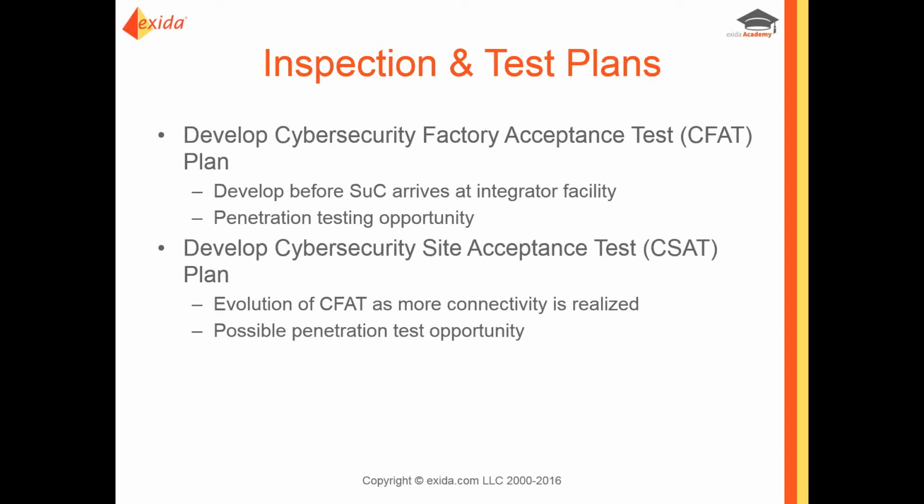You're also going to be developing the cybersecurity site acceptance test plan, after it's been actually installed but prior to startup. That should be an evolution of the cyber factory acceptance test, because now you've got more connectivity, and it's also an opportunity to do potential penetration testing.